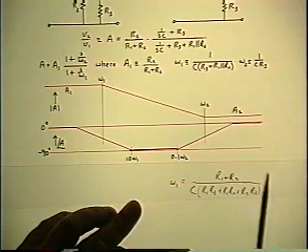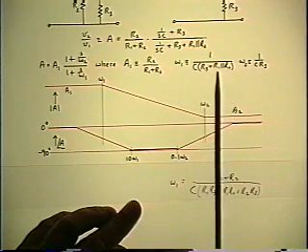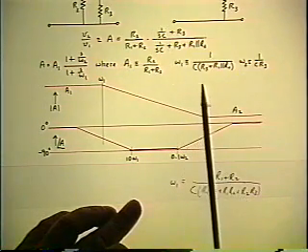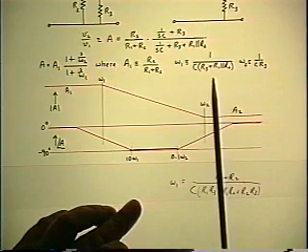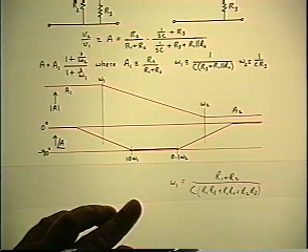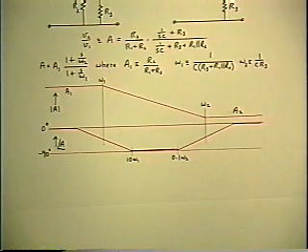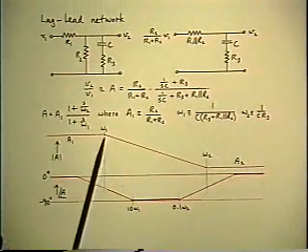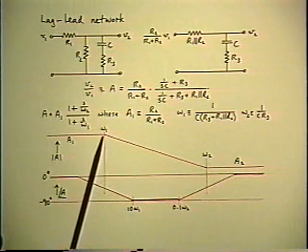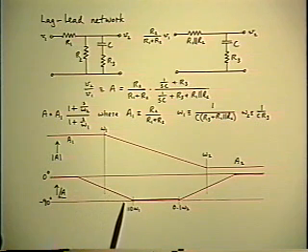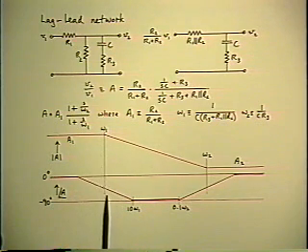So there's another very simple example of the value of keeping the results in low entropy form, or in this particular case, deriving it in low entropy form automatically, and it's simply a matter of not multiplying it out into a big mess. It's always the objective, of course, to avoid the big mess. So in this particular case now, the pole will come first, so we'll have a concave downwards corner at omega 1 with a corresponding minus 45 per decade phase asymptote centered on the omega 1.